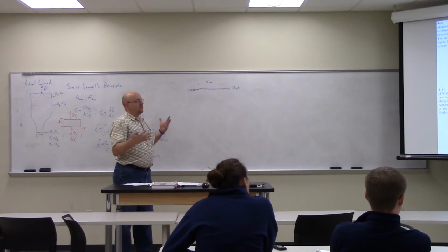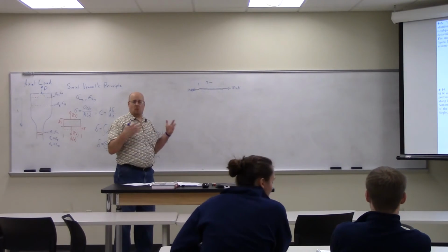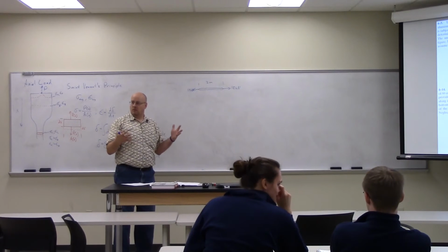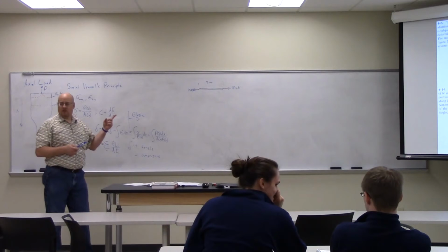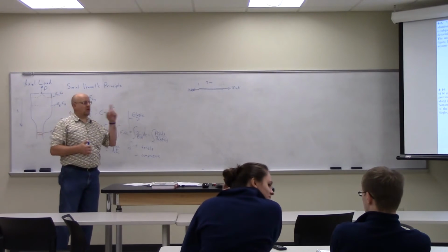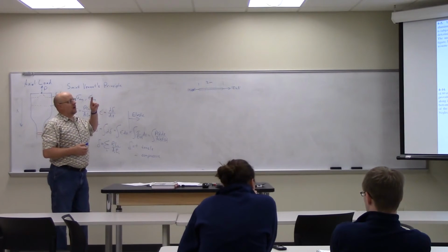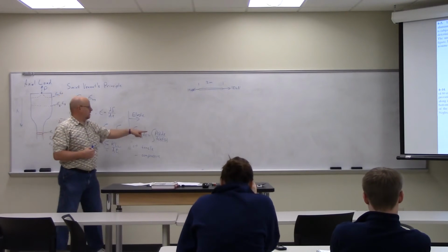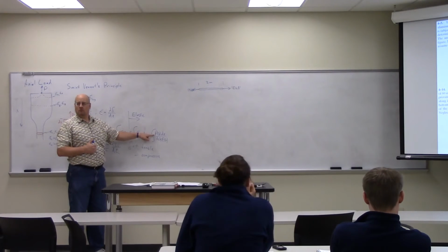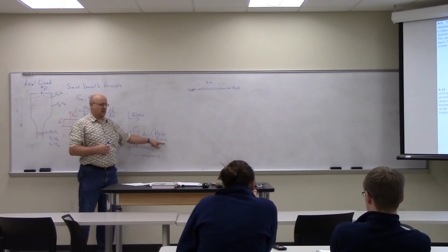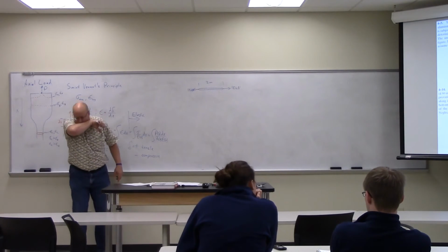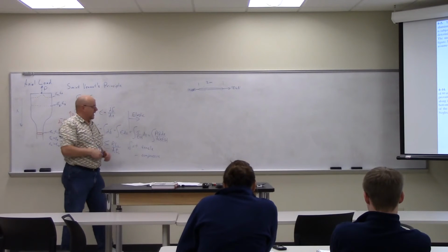So no matter what piece I'm looking at, I need to find the delta. Now that I've chosen this particular body, is P changing? No, I've got a uniform P. There are no extra P's. Is A changing for this sample? No. Is E? These are all constants, I can pull them out.